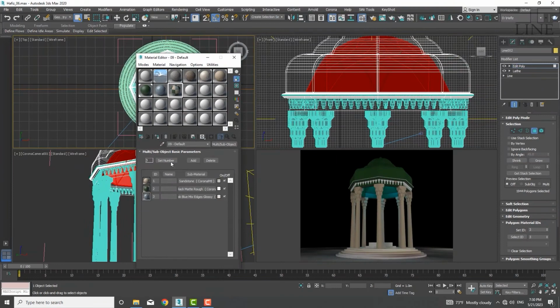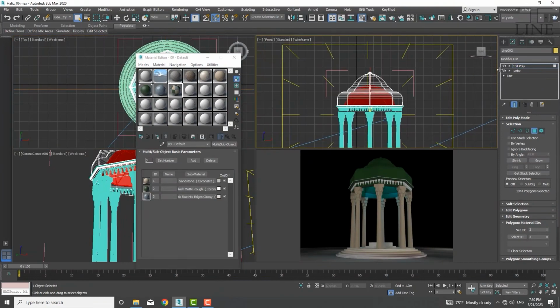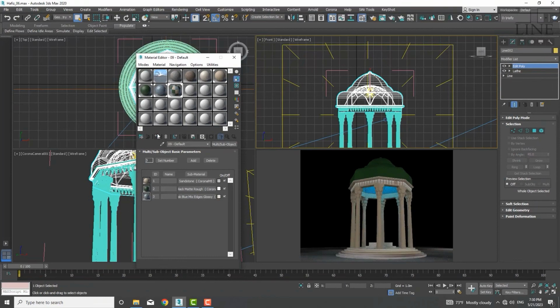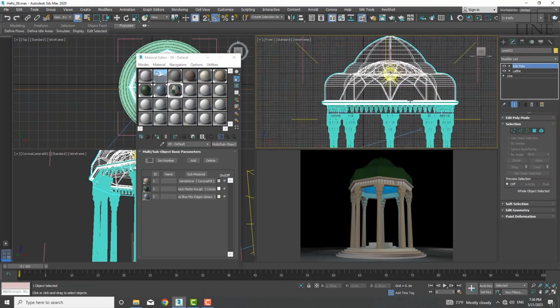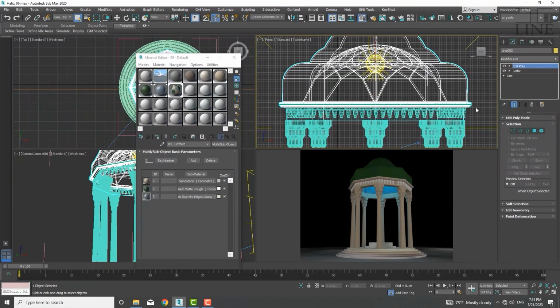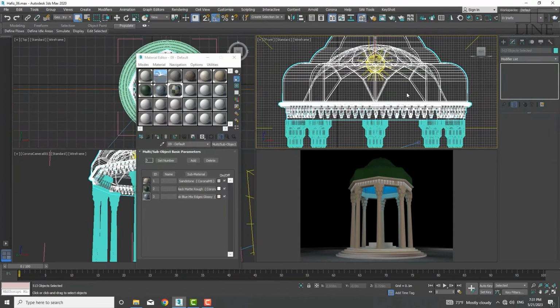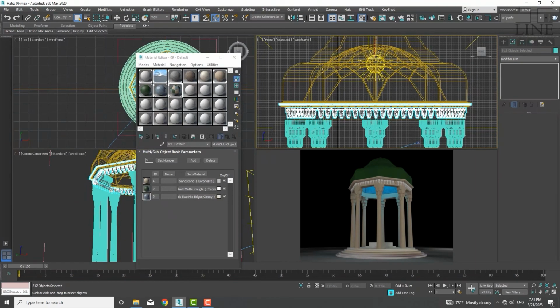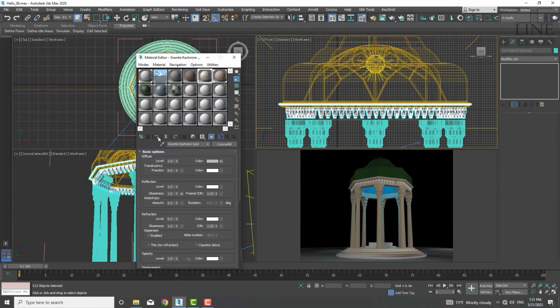And now my material ID. I'll exit polygon mode in Edit Poly and assign this material ID to that volume. You saw that happen to it, and very easily. Based on the ID we gave, it accepted those materials. Those parts of the prayer beads and that mouse teeth, I'll select them too. I'll exit multi-sub object selection and assign the same stone material to them.